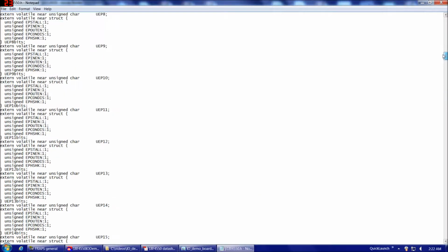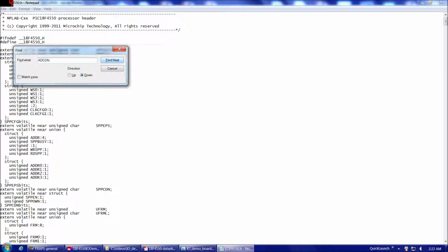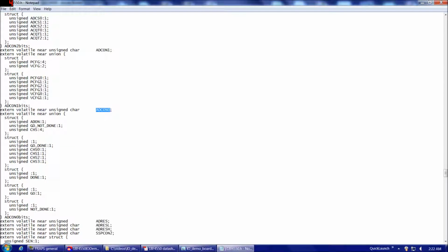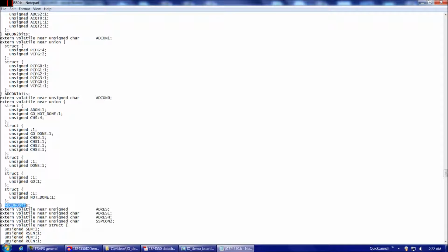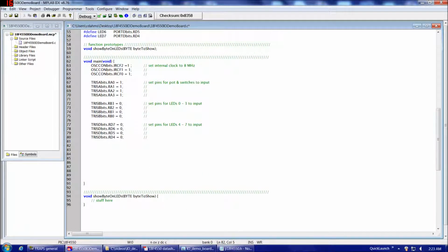So for example, if we go back to the .h file and to the top, and then we search for ADCON0, sure enough, there it is. And here we are down at the bottom, ADCON0bits. And then we're going to use a dot to refer to this inner part of the structures and the unions, how they have them set up. So ADCON0bits dot, and there they are, CHS 3, 2, 1, and 0. Of course the order is reversed because in C, when you list structures, you start with the LSB effectively and you work towards the MSB, whereas the PIC datasheets traditionally do it the other way around, but you get the idea. So let's go ahead and set those first 4 bits.